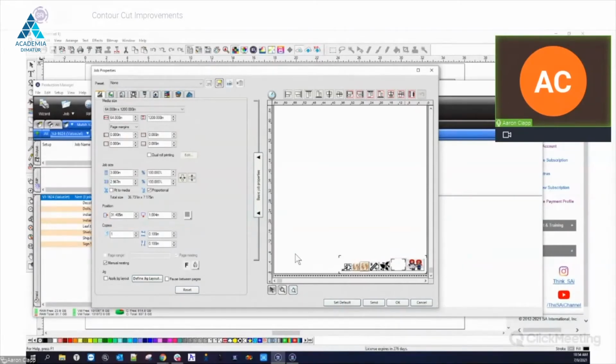Because if it's off at 12 feet, it should still be off a little bit at 12 inches. So it's not going to be near as much, and that's why we say measure it as accurately as possible. Now, if the problem doesn't show up until then, there might be something else going on, or you might need to cut it at, say, 24 inches or something like that. That's why you can adjust that value there. But typically we've found that if the compensation needs to be used, you'll see the problem manifested even on smaller cuts.